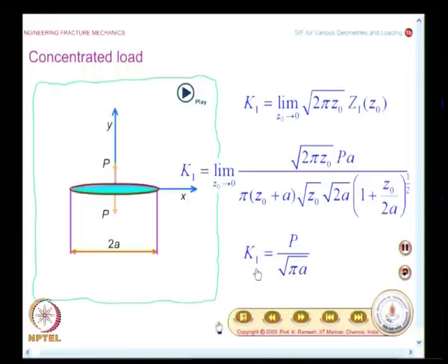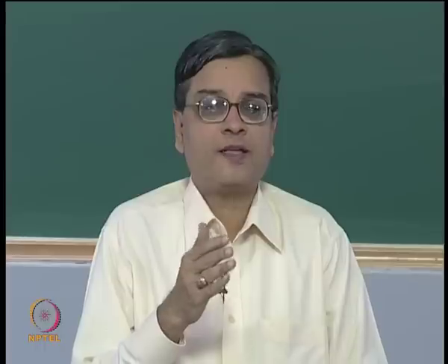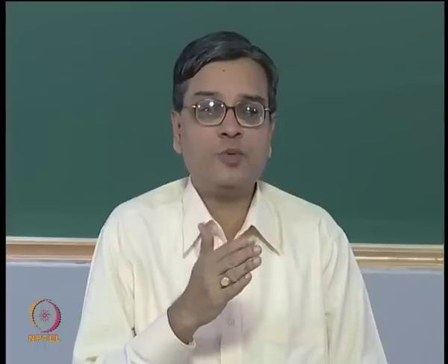It is a very important observation. If I did not have an analytical expression, if I am able to solve only by numerical analysis, then I will have to get the result for various crack lengths, then fit a sort of empirical relation, then observe what the nature is. So, in any problem, if you have an analytical approach and an analytical expression, it is the most convenient form of relation that you can handle.